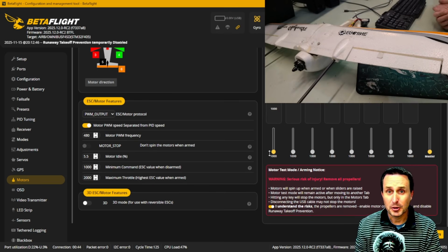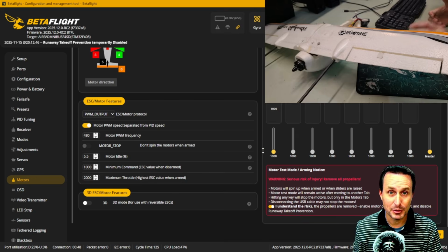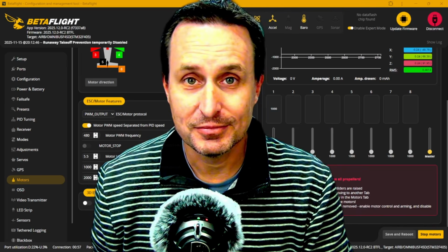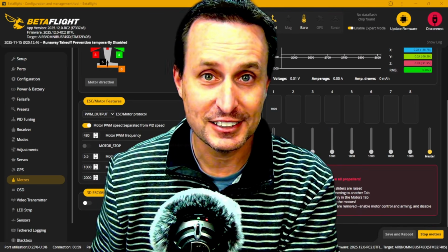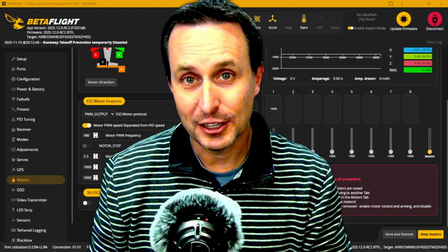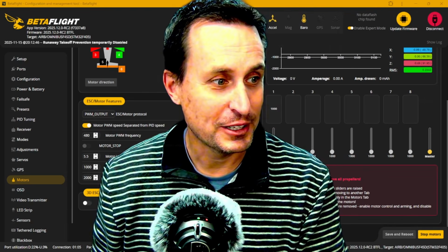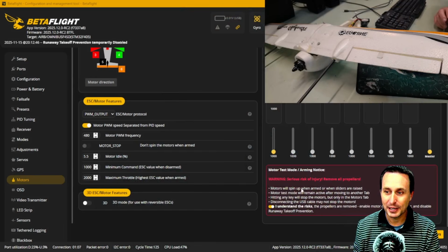Obviously, a reminder, if it's a new wing back before PWM and D-Shot days, let's turn this off. If it's not a D-Shot ESC and you have not calibrated the ESC, just remember you have to do that. So let's talk about that little blast from the past.